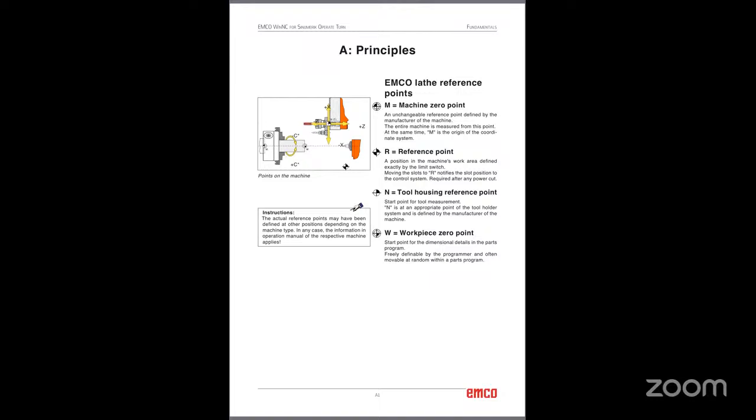So this machine is a PC controlled CNC lathe. We can use different CNC control simulations such as Siemens Numeric, Fanuc, Fagor, etc. So this is working based on the closed loop feedback principle. That means this machine is having servo motor and encoder. If the command is executed, then the servo motor will take the appropriate action based on the command.